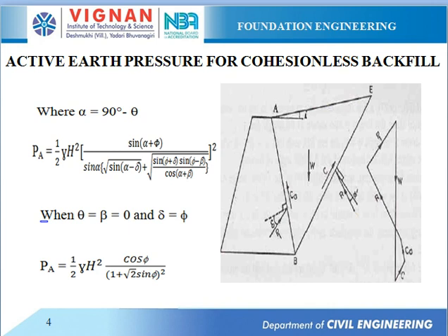The success of the earth pressure theory will lie in the correct determination of the values of phi and delta. It is not advisable to use assumed or tabulated values of phi in earth pressure calculations.